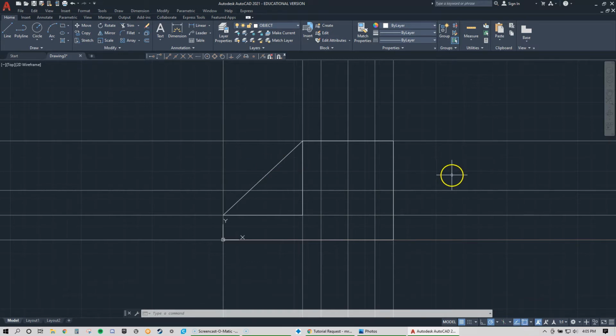Now let's put the circle in. C, enter. Let's come in here. Here's where the center of our circle was. Let's click start to move out. The circle was a diameter of 25. So I'm not going to type 25, because you can see I'm creating a radius circle. So we're going to type 12.5, which is half of 25. There's my circle.